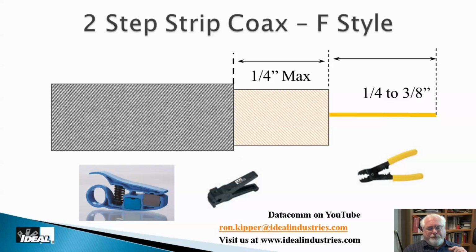So the black one in the middle is what we refer to as clothespin style. They operate and open up kind of like a clothespin, and you can adjust the blade depths in them, okay? The one on the far left over there is an example of something you cannot adjust the blades in. And so with those kind of tools, you have to have kind of a feel for what you're doing with the cable when you strip it, because when they're brand new, you might only have to go around 2 or 3 times around the cable and it's done its job.